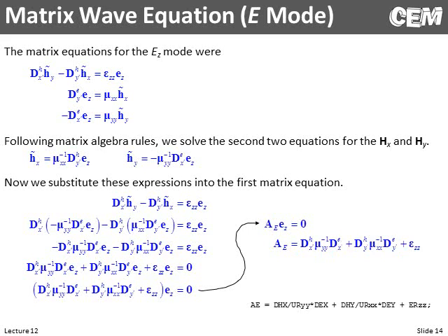Now, we took a really easy approach to get to this big ugly matrix. If we didn't know about these derivative operators, we'd have to be manipulating 6 different finite difference equations, rearranging terms, keeping track of all the indices, and eventually come up with a very big ugly equation that would somehow lead us to populate this matrix. Well, instead, we're going to have a function that can pretty simply calculate these derivative operators, pretty simply construct these diagonal matrices, and then we just put them all together in one line of code in MATLAB, which is right down here. So this will be one line of code in your MATLAB program. That is very, very easy.